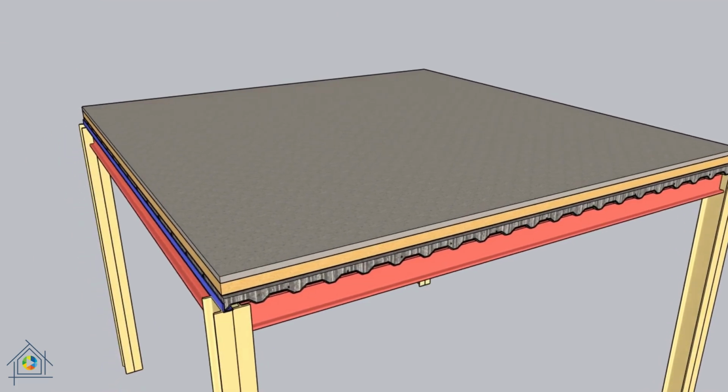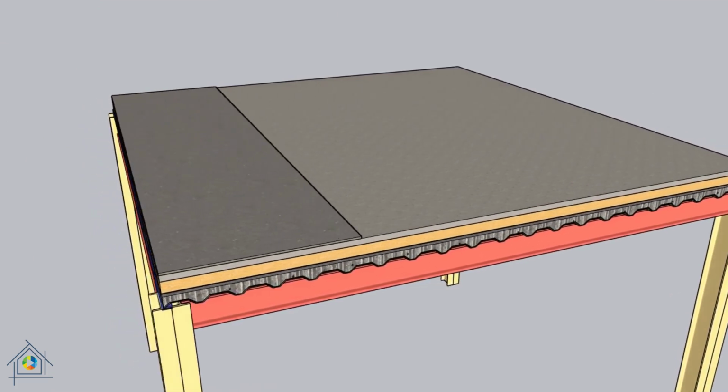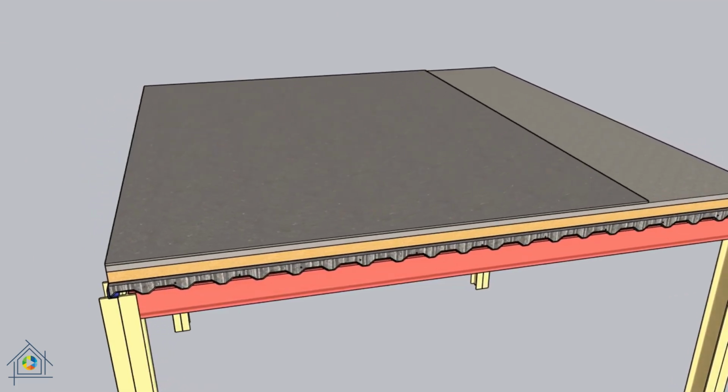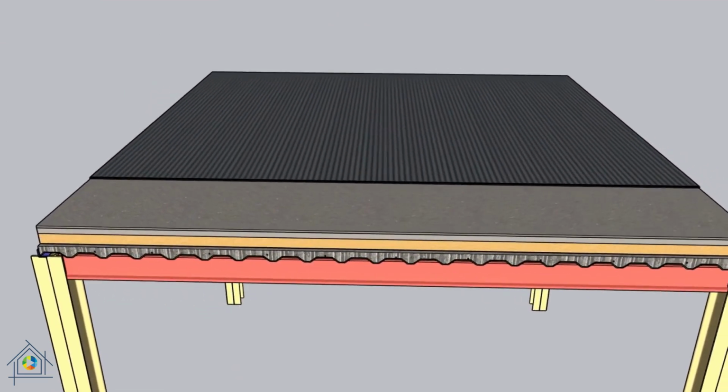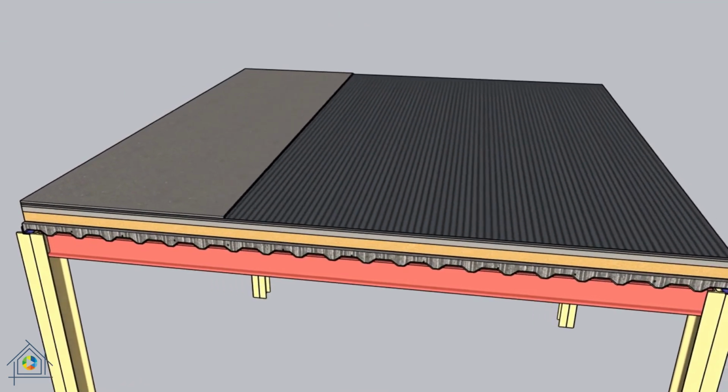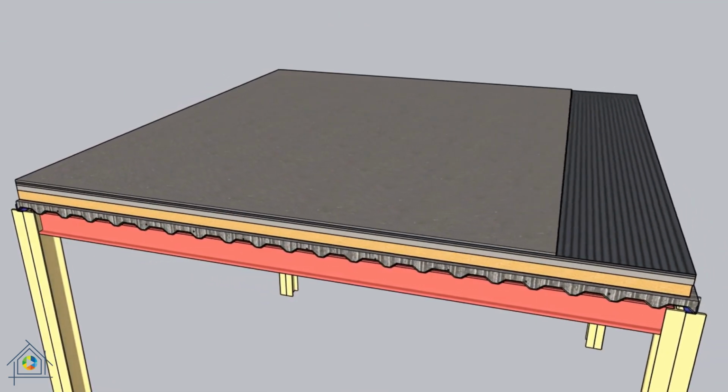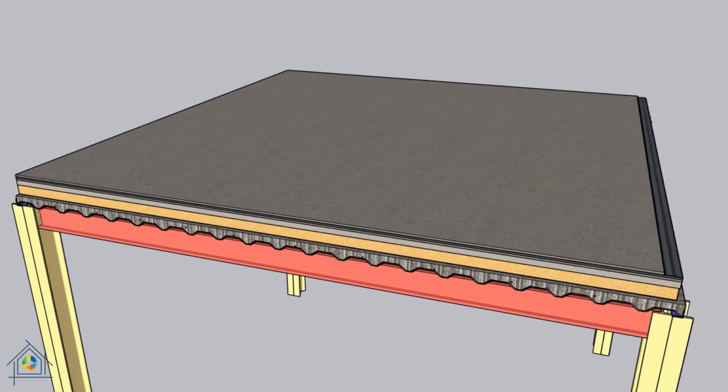The next layer is a moisture insulation that is applied between two layers of sand and cement mortar. The moisture barrier layer can be tarpaulin or prefabricated moisture barrier. The sand that makes up the cement sand mortar must be fine so as not to damage the waterproofing. The two layers of cement sand mortar, in addition to smoothing the surface, also protect the waterproofing. The thickness of the moisture layer and mortar is at least 4.5 cm.